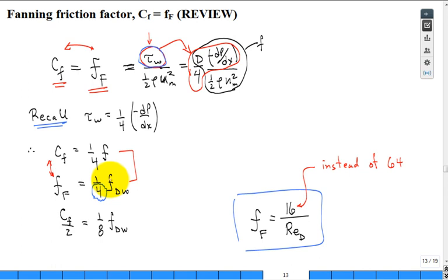So, I hate to say it, sometimes they're a factor of 4 different. Sometimes somebody will say, oh, the friction factor for flow inside a pipe, laminar flow, completely fully developed is 16 over the Reynolds number. You say, that's a typo. They have a different definition of the friction factor. It's 4 times 16 is 64. So do you remember something like that in your fluids book? I hate to say it, but the world isn't consistent when it comes to friction factors.